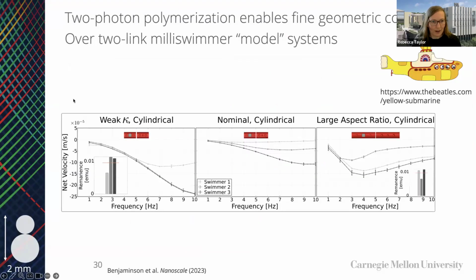This is our little yellow submarine project, where you could see that depending on K, so depending on the stiffness of our connector, we saw changes in the maximum velocity of our system, right? And so there is, at least in this regime, a softer spring gives you better locomotion, which makes sense because you have to break the scallop theorem. If you've got a rigid object at the micron scale and low Reynolds number, in order to have a non-reciprocating gait, there has to be kind of a lag between the two pieces moving. Otherwise, you can't locomote. You actually can't move in low Reynolds world.